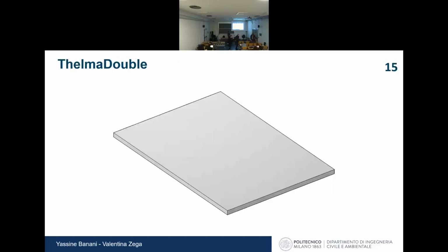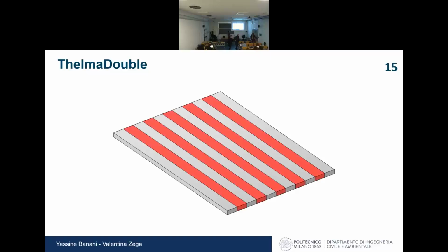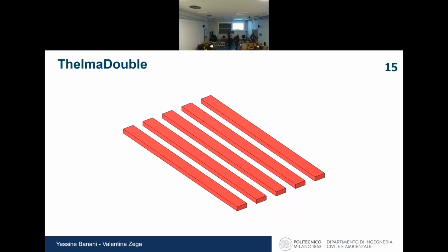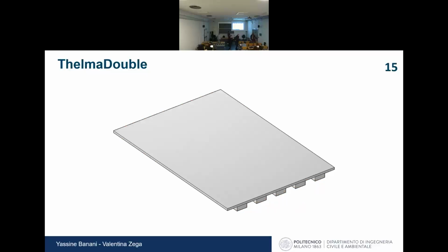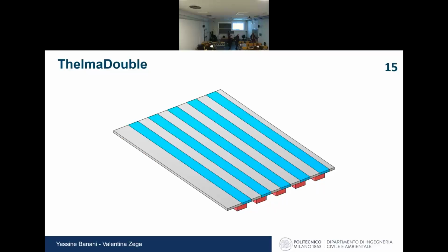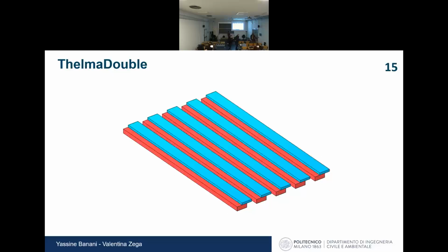Let's start from improving our fabrication process. So a piece of silicon, we protect some areas, we delete all the remaining areas, and then we attach a second layer of silicon. We protect different areas, and we eliminate the remaining areas. So this is a double layer system. This is overly simplified, what we call the double thermal process. It was developed by ST Microelectronics, a company that produces MEMS, in which we have two different layers, and we can control both of them.